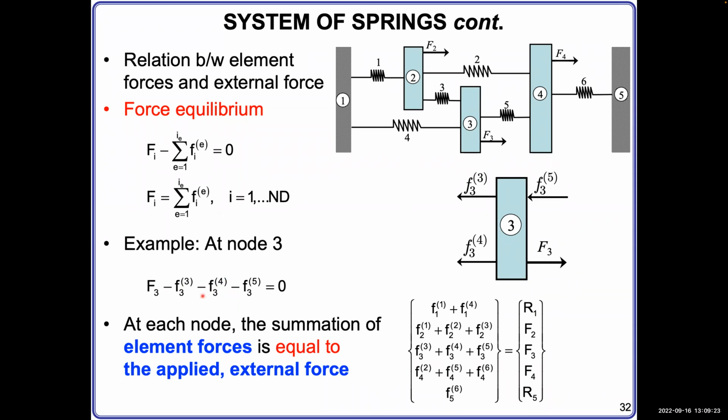And then you can calculate that. If you find in the results that any force is positive, that means the direction we assigned in the first place is accurate. If you find the force is negative, that means the direction should be opposite with respect to the originally assumed direction. So this is very straightforward. Just use this convention to solve the force there.